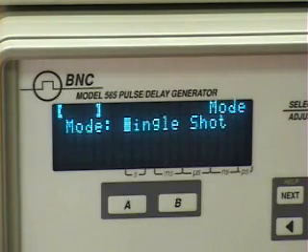Let me talk a little bit about the jitter. External trigger coming in, 8 channels going out. The jitter between the 8 channels is synchronized to better than 1 nanosecond. If the channels are close together, the jitter will be on the order of 250 picoseconds. However, the jitter between the external trigger and the output channels themselves will be on the order of less than 5 nanoseconds RMS.